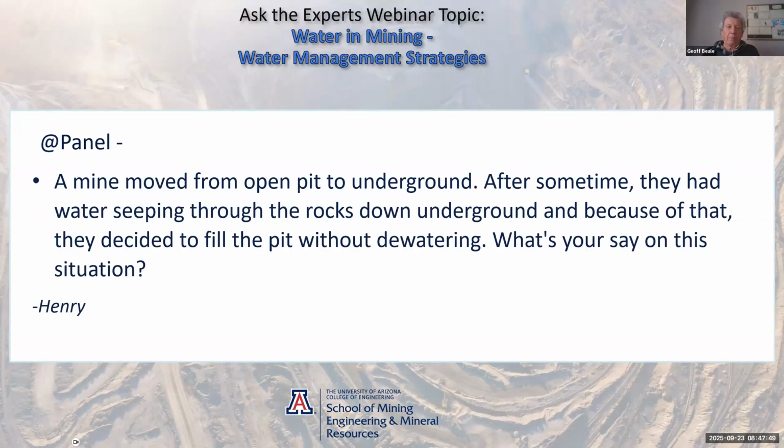You're just burying the problem, I think. Correct. And I agree. If you can fill it with tailings, there's a number of mines that put tailings into pits where they're working underneath, and that can reduce the dewatering rate and reduce the recharge, and that's good. But if you do that, you have to be pretty careful that your settlement and subsidence from your underground mine doesn't allow the tailings to pipe and allow a tailings failure to suddenly go into the underground.